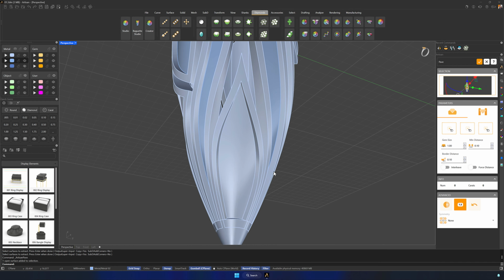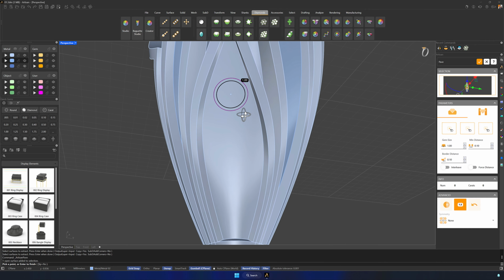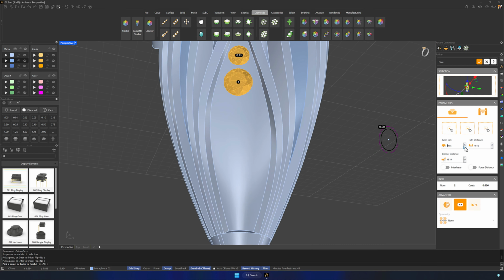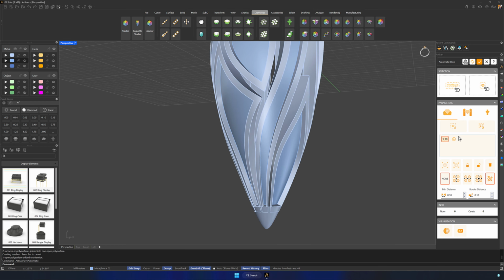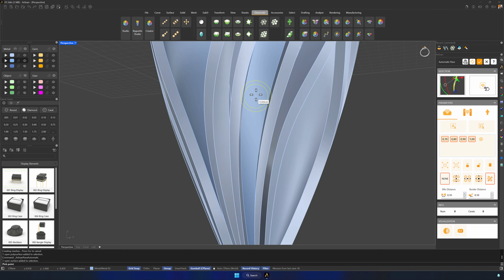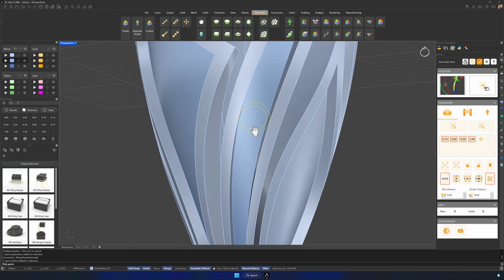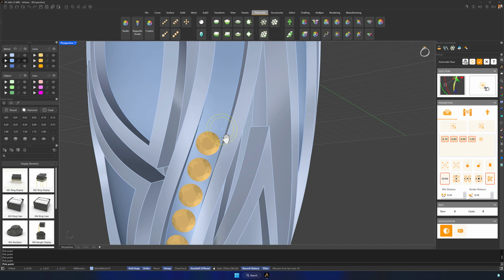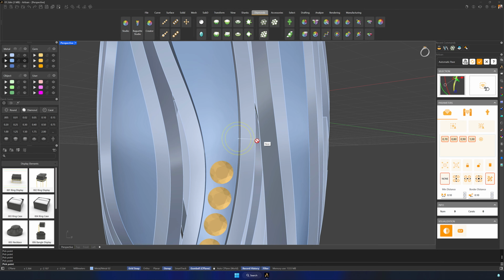For example, we go to Add Diamonds, assign the surface, and start placing gems. We can start with 0.75 millimeters, using the guides, and place them to our taste. For this smaller area, I'll use Automatic Pavé. I assign the surface, set the gem sizes I want for this section, and then decide where to start. I choose a gem size, check where it fits, and place the first one. Then, following the guides, I keep placing gems.